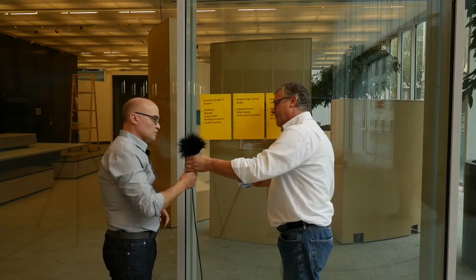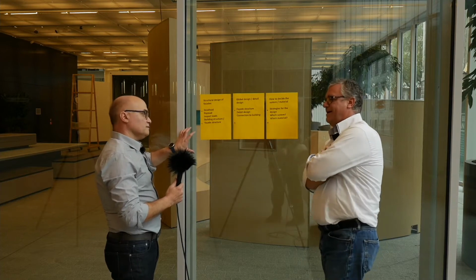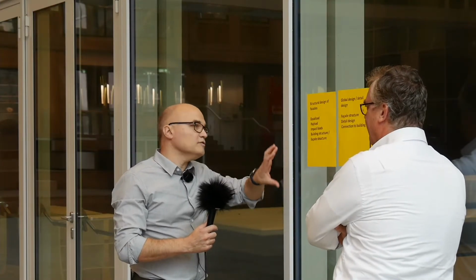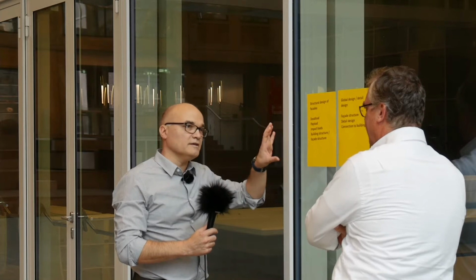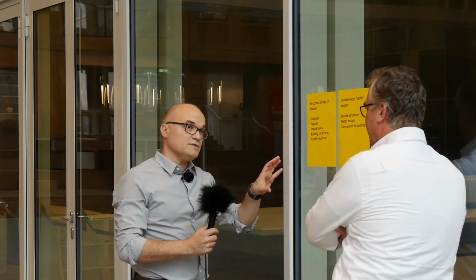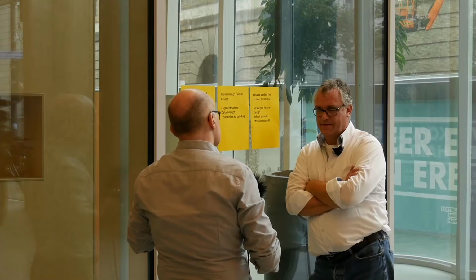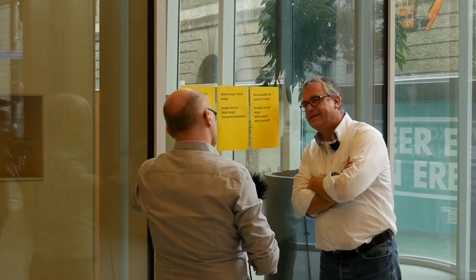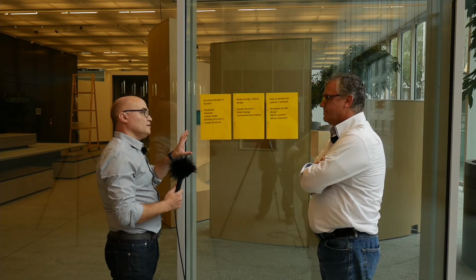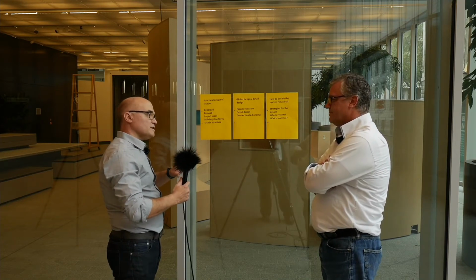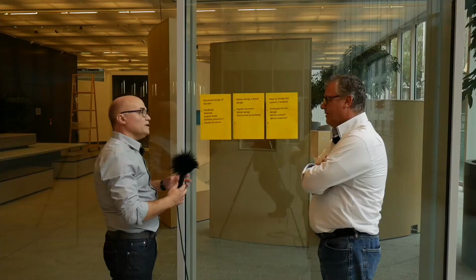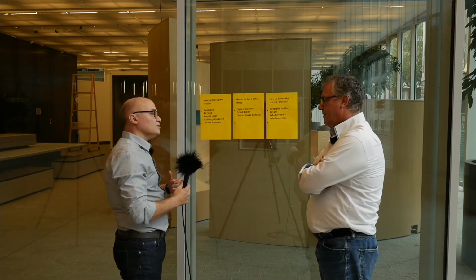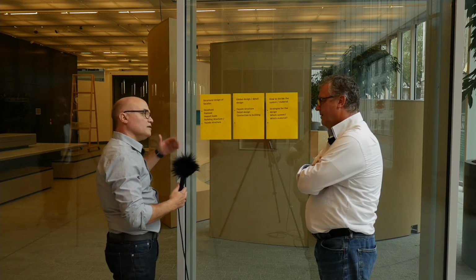Yes, very good. So you have the main structure, which is made of steel, concrete, or timber, the main load-bearing structure of your building. And your facade structure is quite often made of other materials. It might be made of aluminum or glass. So these two already have different movements. The facade and the main structure might expand and contract in different ways, so you have differential movement. In order to deal with that, you need to make sure that you leave an expansion tolerance for movement between your facade and your main structure.